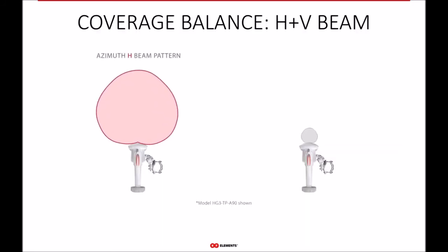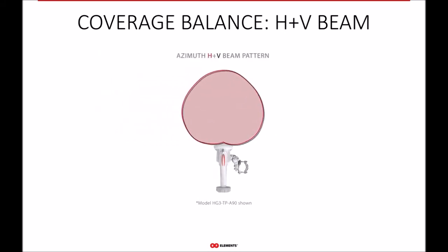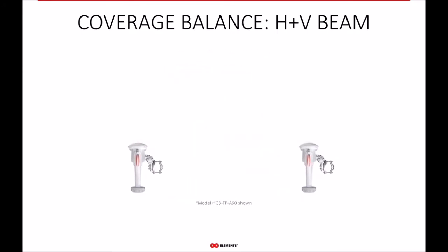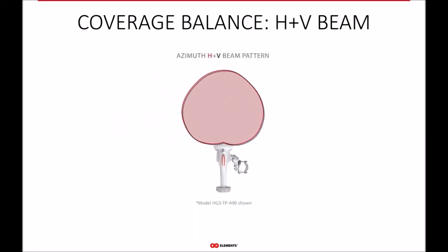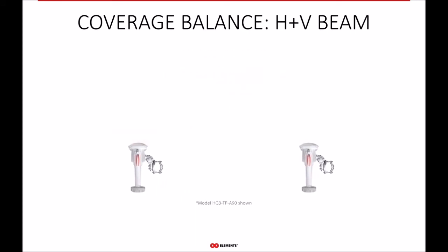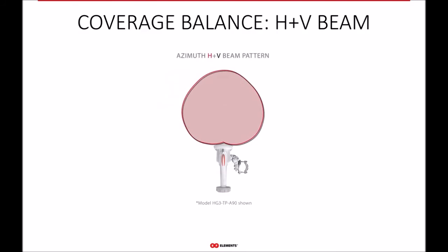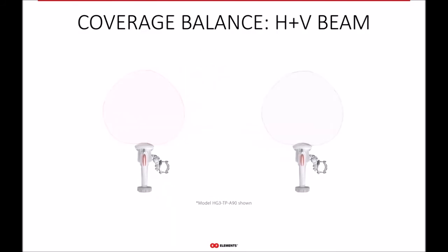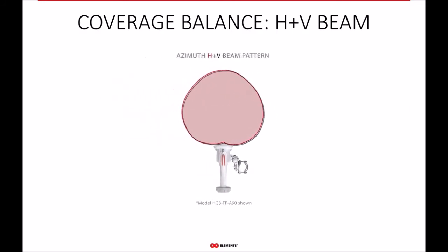Another component of the coverage stability is the balance between the performance of the horizontal and vertical antenna systems. So asymmetrical horns have the same radiation pattern for both polarizations, which perfectly fits this stability criterion. So you don't have to worry about the customers on the edges of the sector when you switch from the horizontal to vertical chain. In comparison, the competitive patch array sectors have unbalanced horizontal and vertical systems, which has a negative influence on the field performance, but hey, more about that in part 2. Let's not go ahead of ourselves too much.